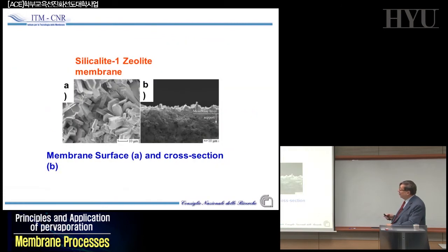I was mentioning that one of the cases of interest today is one of the first cases where there is basically no competition for inorganic membranes, just in pervaporation. This is the structure of a silicalite zeolite membrane, where the Japanese have been able to realize an asymmetric, in this case ceramic, membrane, forming a relatively homogeneous and non-porous layer of zeolite crystals on some support.